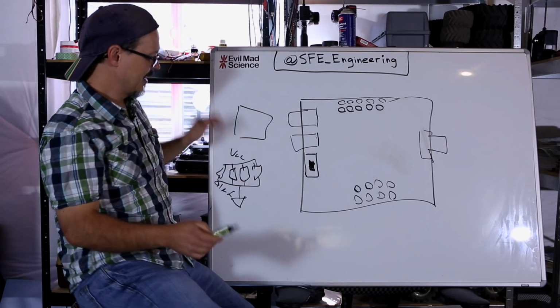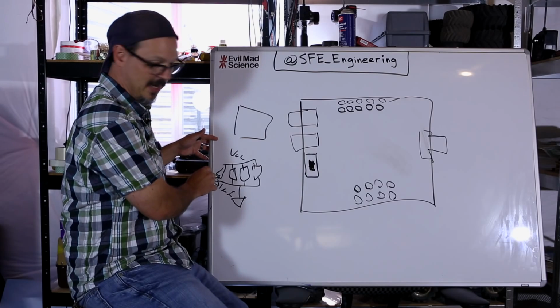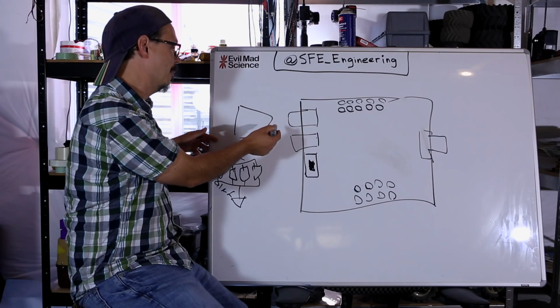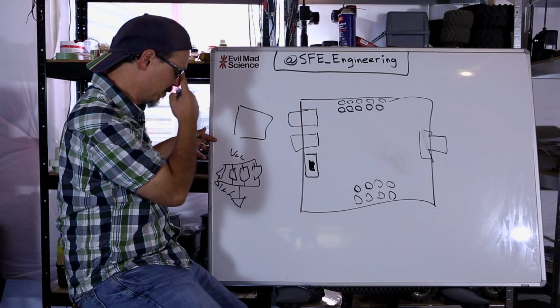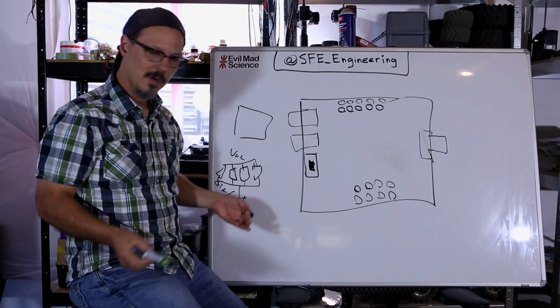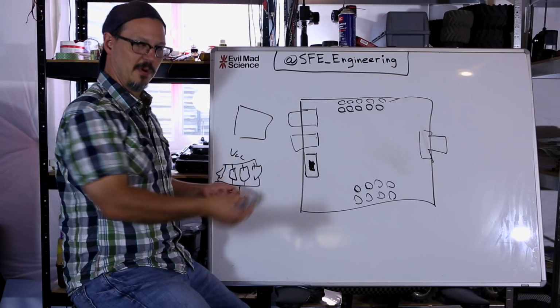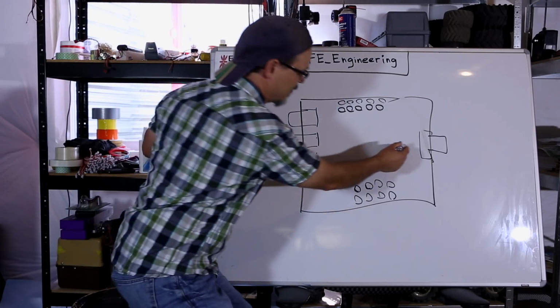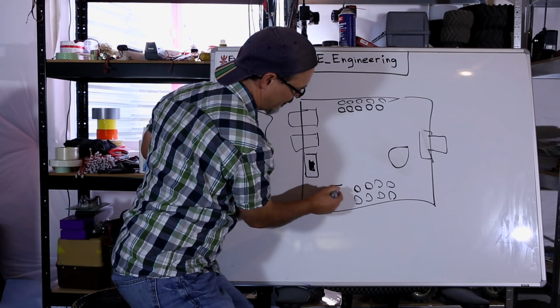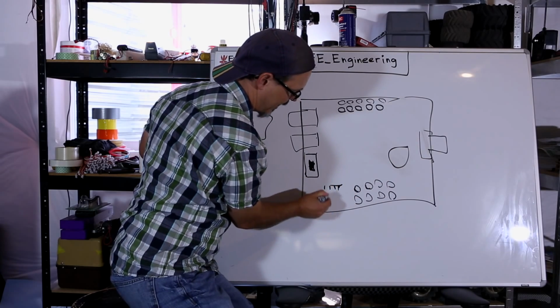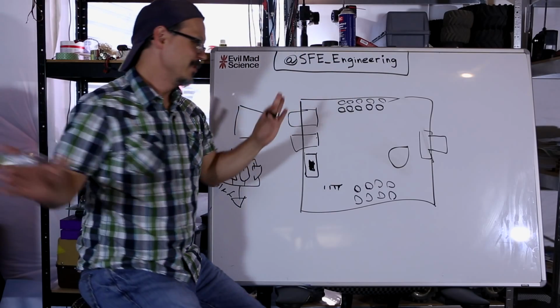Okay. Now, a lot of times in the schematic, you'll see it says near pin such and such, referring to the microcontroller. And what some people will do is they will just say, well, I could just put all those together in a section, right? So you've got your microcontroller over here. Oh, well, I had some room over here, so I put all my caps here. No, you don't do that, all right?